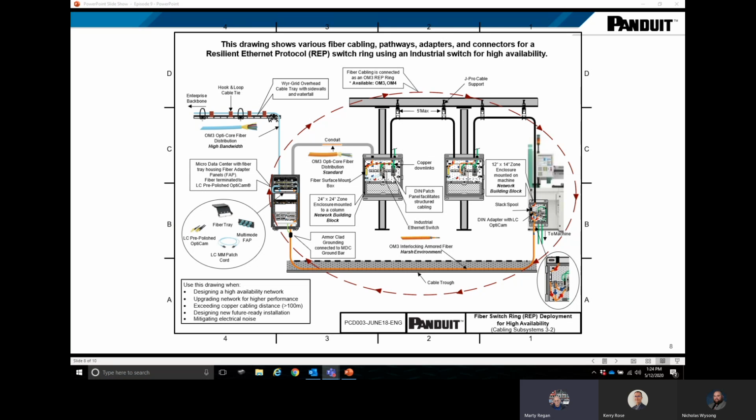Cable tray provides closely spaced support and is used with indoor type fiber cable. Waterfalls and intersections can easily be incorporated into the pathway to protect bend radius. Conduit provides continuous support for indoor type fiber cable. It's an excellent safeguard for a fiber pathway, but fittings, junctions, and breakouts can pose a challenge during pulling. Finally, we have J-hooks with bend radius control built in to provide spacing support at 4 to 5 foot intervals for metal armored type fiber cable. The armor provides the needed rigidity to prevent cable sag. We'll have more discussion on these supporting products in episode 12.